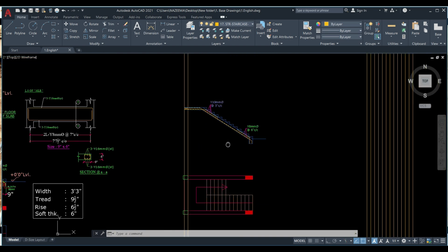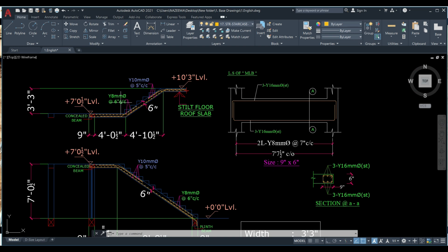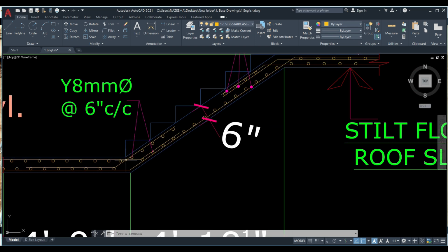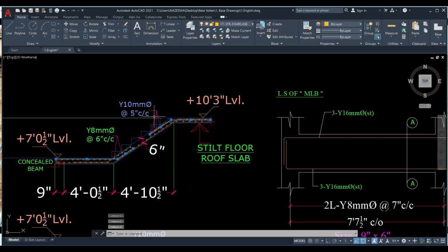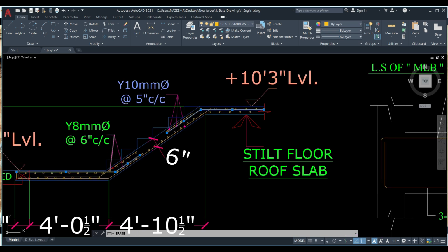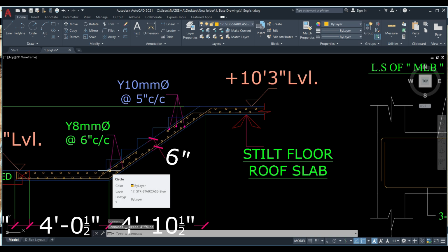Now whatever steps I have shown you, you have to just repeat those steps for this particular part. Okay, again, what they have done here is they have given some additional amount of reinforcement over here. This is additional reinforcement, and this is additional reinforcement. Now this can be done on bending. Even if you create a bending moment diagram, you won't require this additional reinforcement, right? But it was a request from our contractor.